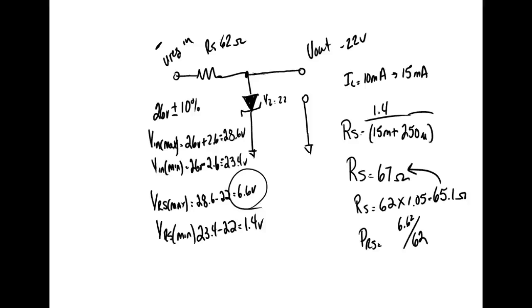So what did y'all get? Yeah, we just round this guy up. This is milliwatts. So what are we going to have to use there? There's no such thing as a 702 milliwatt. I gave y'all the values. So we got an 1/8, then we got a 1/4, then we got a 1/2. You put a 1/2 watt in there, it's going to burn it up.